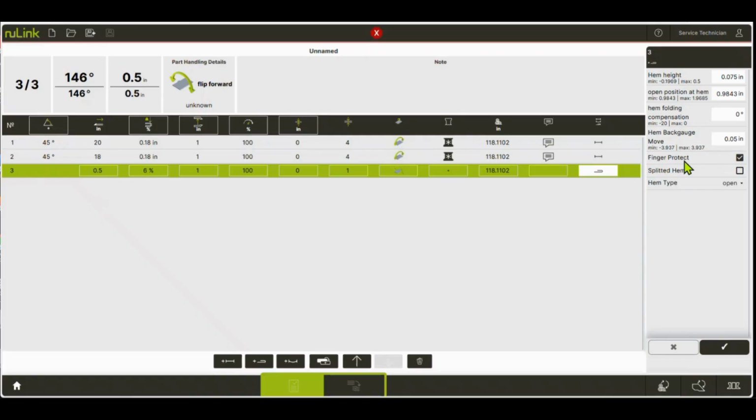And when the upper beam comes down and makes contact with that material, holding it at right around the safety stop opening height, when it reaches that point, the fingers automatically back up about 1/4 inch. So they get out of the way. And then the machine does the final clamp. That way, when it clamps, it's not rubbing that material up against those back gauges, okay?